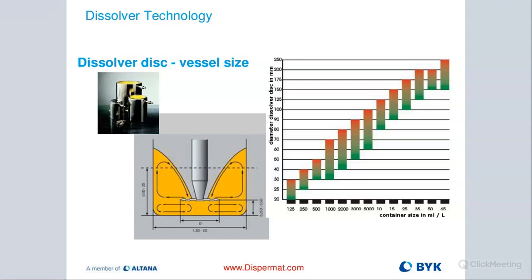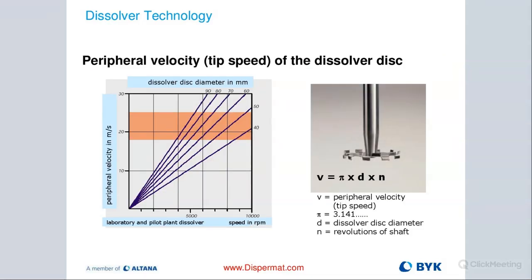So we really need to dial it in, but ideally we always want to get started with about a 1/3 the diameter of the vessel as optimum. And that would also mean good viscosity. So optimum viscosity when you're dispersing, where you can put in a good amount of energy, is anywhere between 2,000 to 5,000 centipoise, because that would give you also that donut effect, that is that visual cue that will then allow you to actually see what's going on inside of the container, and also allowing you to put in a good amount of energy. Lower is fine also, and more is also okay, but you don't have that nice donut appearing.